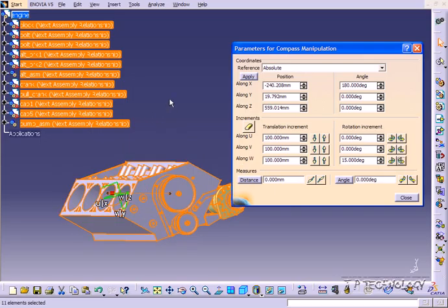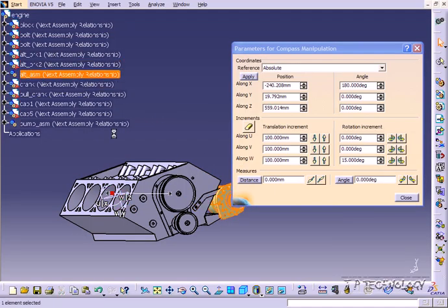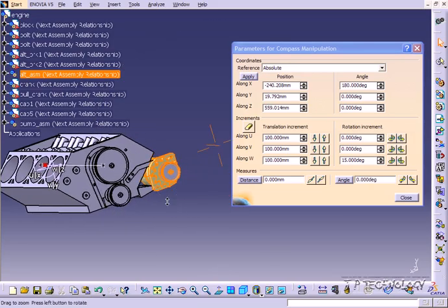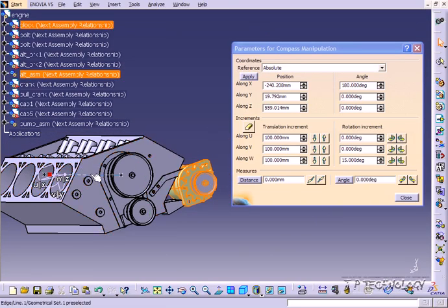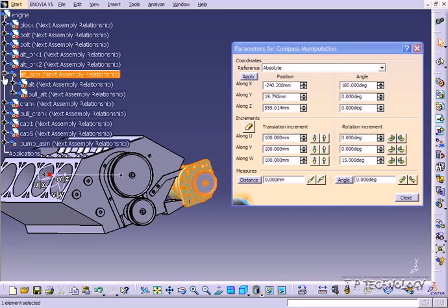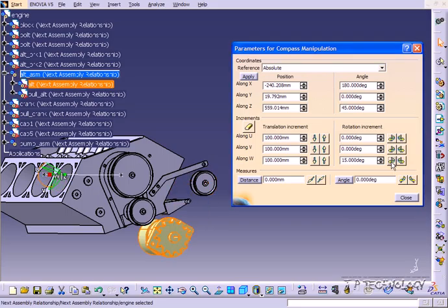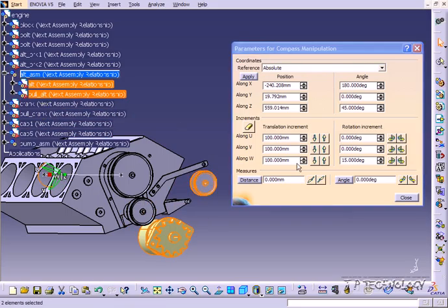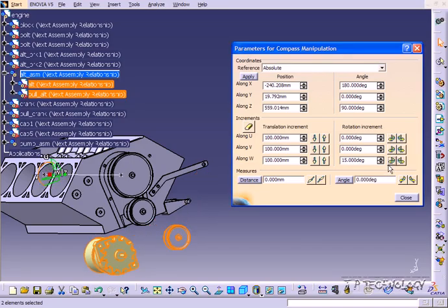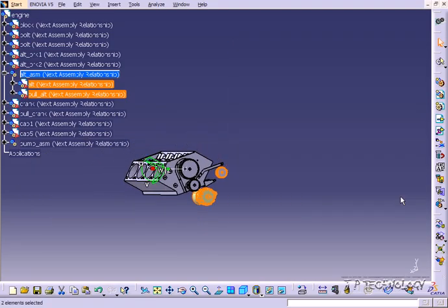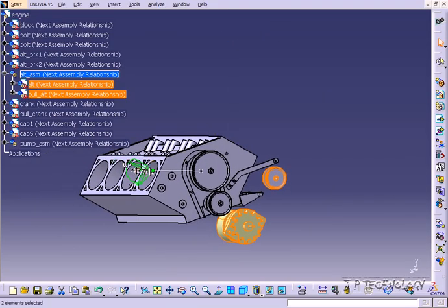And again, we can do this to a smaller assembly. So double click the alternator here. And we're still going to use this as our axis point. Open it up and let's just rotate this one guy. And you can see that only he is rotating. And as we select both, we're able to rotate both at the same time. So again, this works by using this axis that we've created, and this is going to create a consistent axis. So every time we go to rotate, it's always going to be the same result and the same rotation that you get.